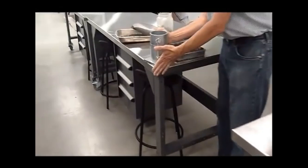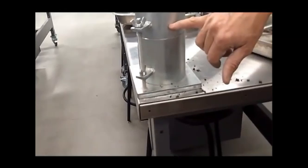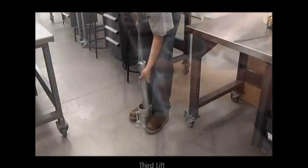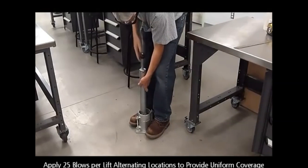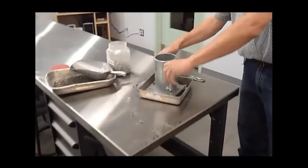Next, I'll take my final layer. I'll add some more soil and fill it up to this point so that after compaction it approximately fills the full mold or a little more than the full mold. Again I'm giving 25 blows for the third layer. Now after giving 25 blows, it must fill the complete mold or be just 1 centimeter or 1.5 centimeter more than the mold.